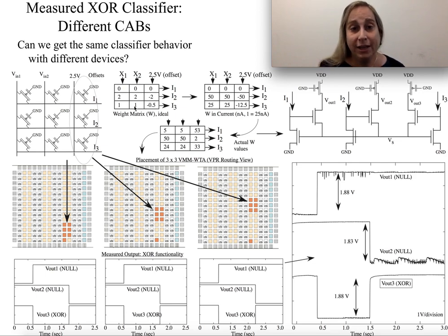Okay? And so you say, well, how do I look at this in practice? Well, I would ideally like to put this in currents. Now it's maybe 50 nanoamps, 25 nanoamps, and still 0 with then the offset. So I just scale this accordingly. Now my bias current is basically 25 microamps equal to 1. There's a scaling term that goes on here.